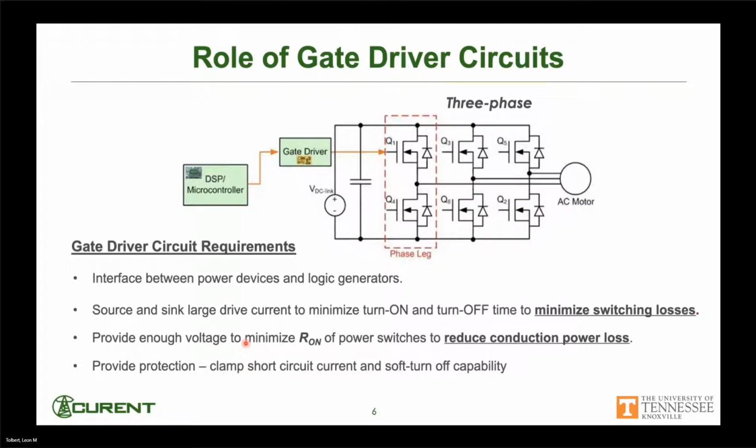So just to get everybody on the same page, I'm assuming that most everybody here is power electronics, but some of you may not be. This is showing a circuit for a motor drive, a 3-phase motor drive, full bridge. Basically, this is referred to as a phase leg. A motor drive, of course, drives an AC motor, and by controlling these switches, we can control the voltage through PWM that controls this motor's speed. Typically, it's connected to DC, and the output is a variable frequency, variable voltage.